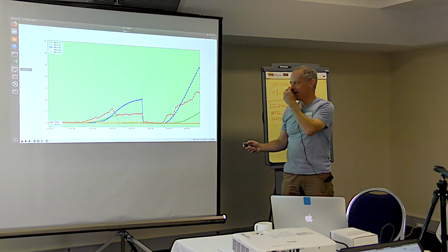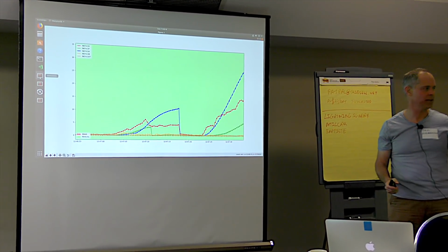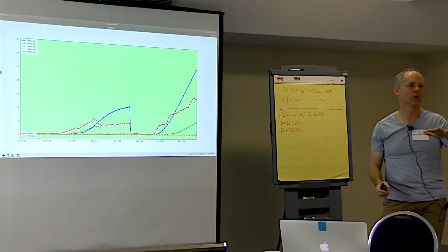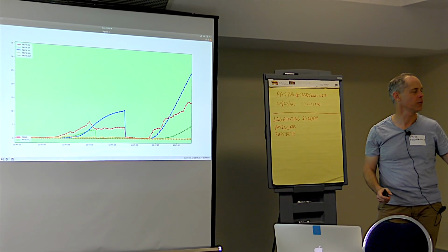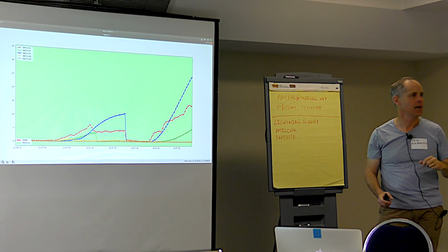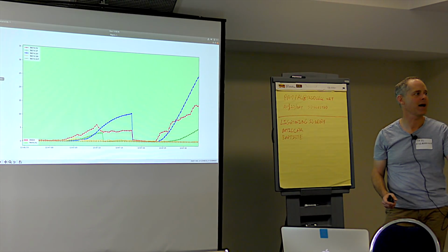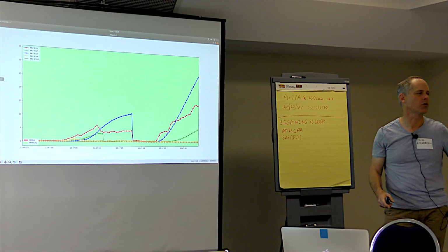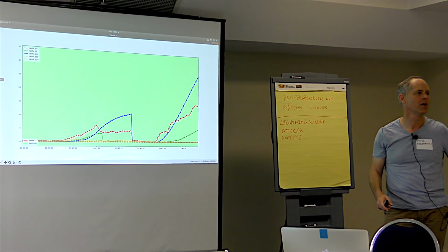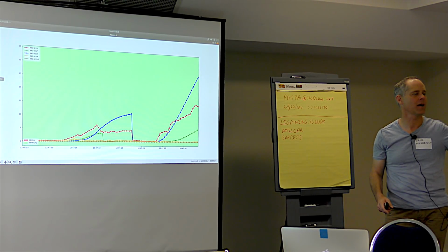These normalized innovations are the ratio of the magnitude of the innovation and the maximum level that the EKF will accept and still use the data. So if it's above 1, it's a fail. And we also show on Mission Planner little bars that show the values of these normalized innovations. I think green is below 0.5, then amber from 0.5 to 0.8, and then red above 0.8.